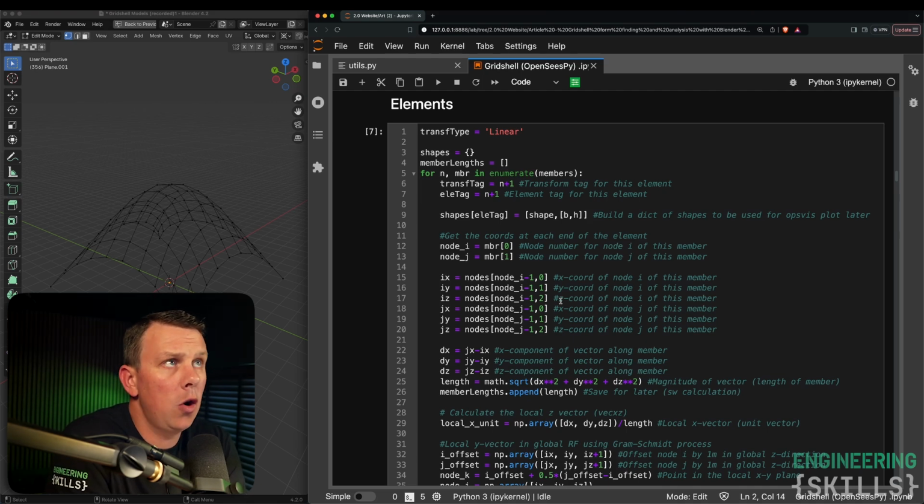And so in OpenSees, the way you do this is when you're specifying the element. In fact, before you specify an element, you have to specify a transformation, right? A geometry transformation or a geometric transformation. What that is really doing is you specifying which way that element's cross-section is oriented about the longitudinal axis of a given particular element.